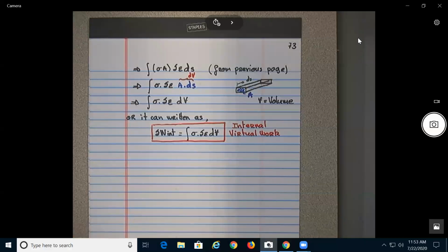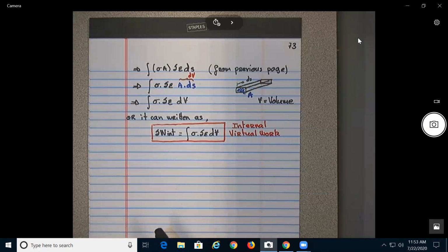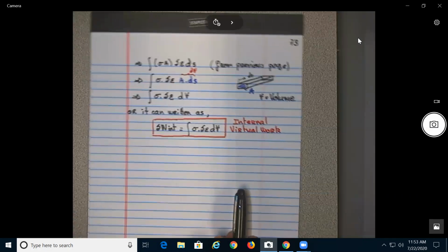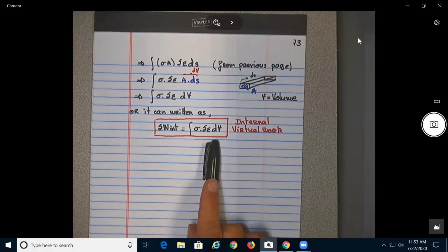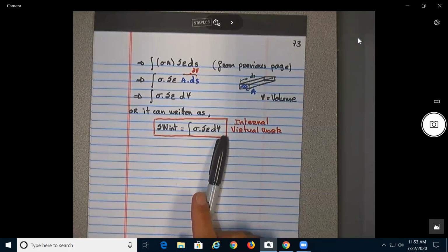Okay, so just like I was saying, this is extremely powerful, even though we're not going to go through the basic derivation and everything, but this equation here is what is behind the finite element method. Okay, what you do in finite element is that you assume a deformation, and you determine for the structure all the different cases.